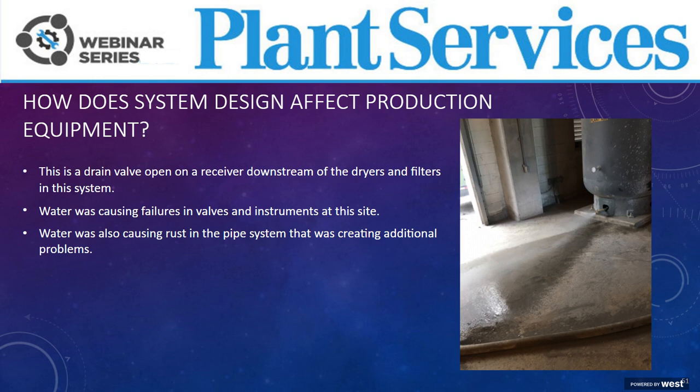That plant had been having problems with cylinder failures, solenoid failures, and all kinds of equipment failures because they were getting water downstream in their system and draining water out all throughout the plant. All of this was because they had improperly sized the drying equipment and the cleanup equipment and didn't take care to keep an automatic drain on their dry tank so that they would know that they're getting water in the dry tank.